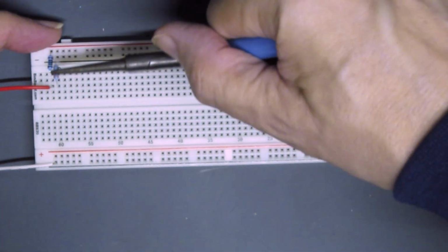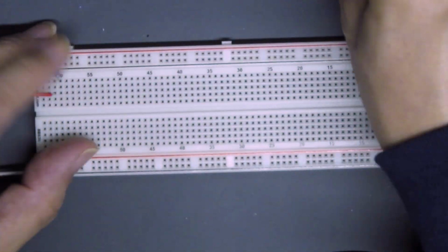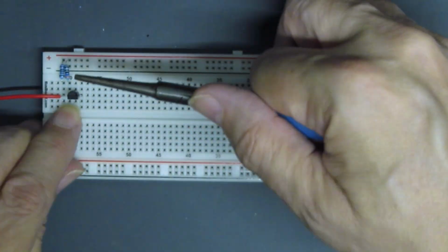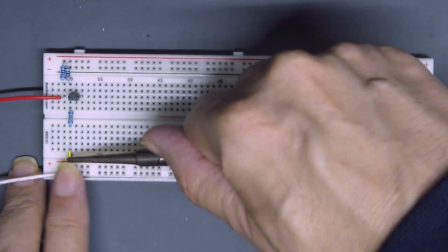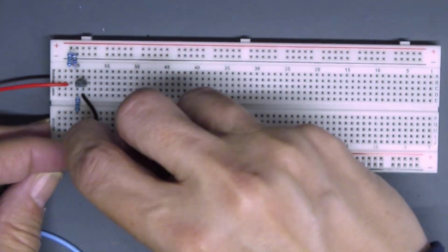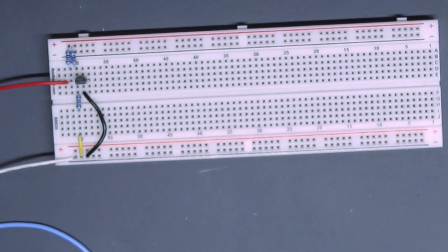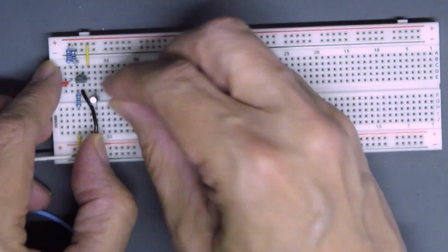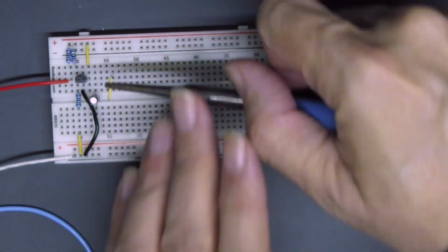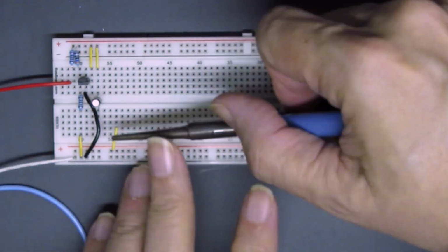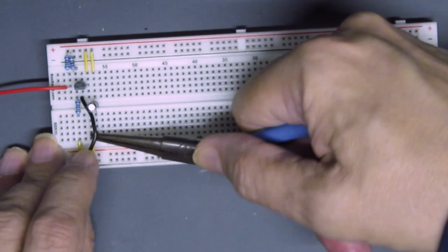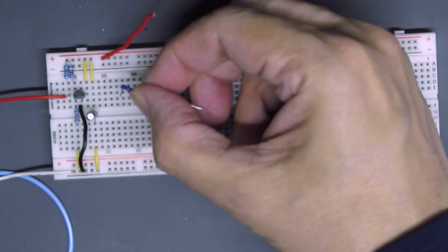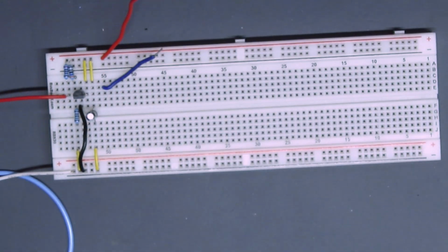I'll add the upper resistor of the voltage divider and the TL431. Then the lower resistor goes to ground. The anode of the 431 gets grounded, and the cathode goes to the 7.5 volt rail. The 10 microfarad bypass capacitor goes in between the power rails. This is enough to test whether the circuit is regulating with no load. So I'll stick in a couple of test wires and hook up a couple of multimeters.